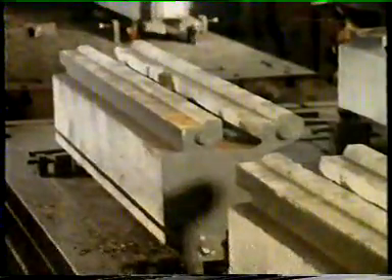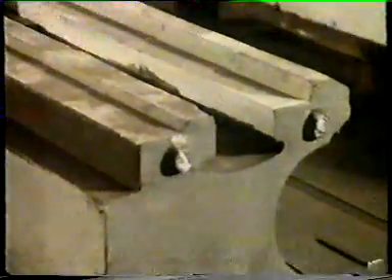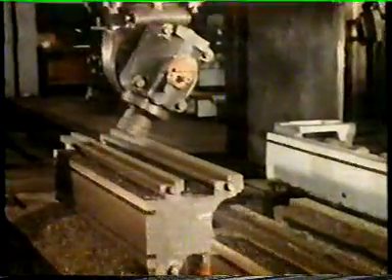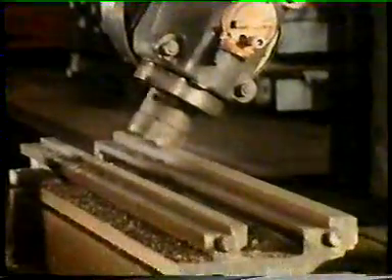However, by heating and cooling steel and certain other materials in a particular way, we can bring about permanent changes in their properties. These castings are made of one such material. They're lathe beds. In this cast state, material is relatively soft and easily machinable, so the large quantities of unwanted material can be removed by milling.